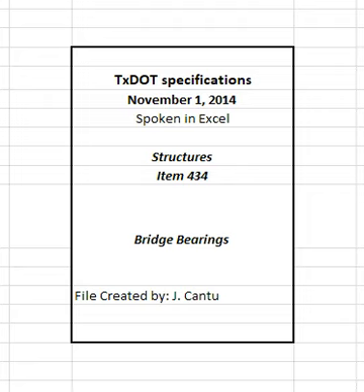Provide a design that meets the current versions of the TxDOT LRFD bridge design specifications and TxDOT LRFD bridge construction specifications. Assume the plan rotations do not include requirements for uncertainties and construction tolerance stipulated in the TxDOT specifications unless indicated on the plans. 2.3.2 Maintenance functionality. Provide a fabricator-developed design that allows future removal with a maximum vertical jacking height of 1/4 inches after the load is removed. Provide a design with minimum 4 inches distance between the bottom of masonry plate and top of sole plate.